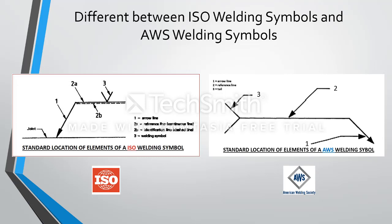For ISO, it has an arrow line, a reference line, which is a continuous line, an identification line shown as a dash line, and the welding symbol itself. For the AWS welding symbol, it only has an arrow line, reference line, and tail line.